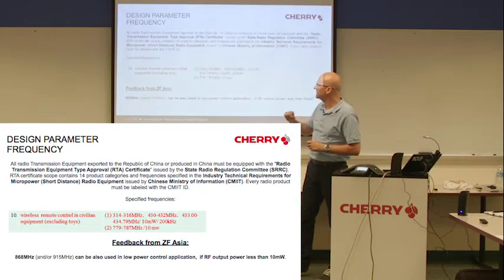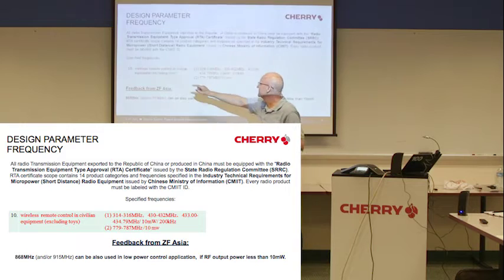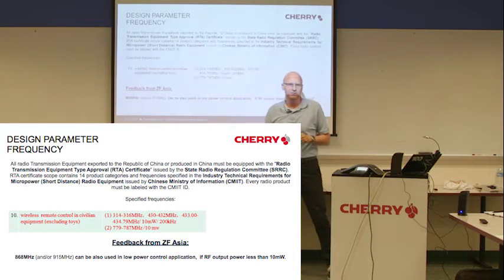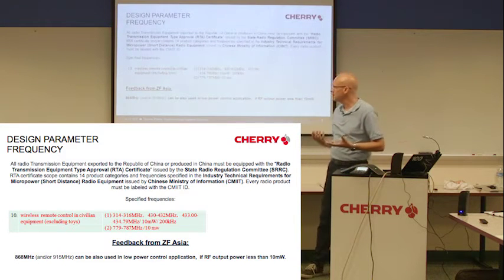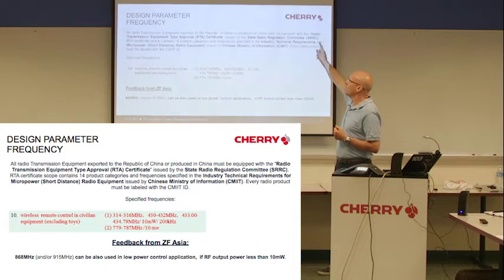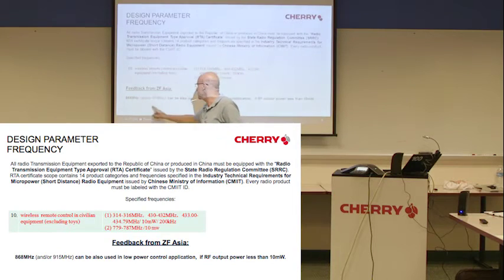We find a device category where our product fits in, and you can use different frequencies, for example 433 MHz, but we don't have such a product. So we go to the regulation committee, the SRRC it's called in China, and say, what about 868 megahertz or 915? And they said okay, you can also approve products to this frequency.